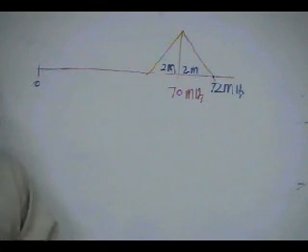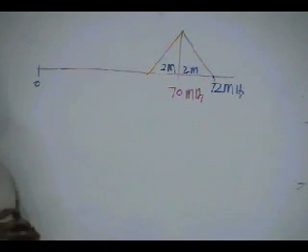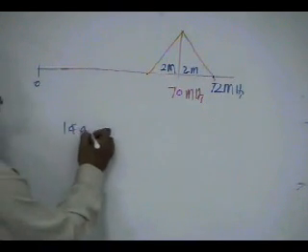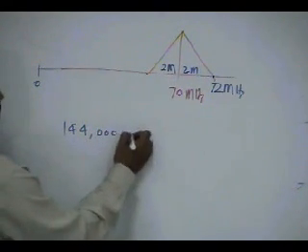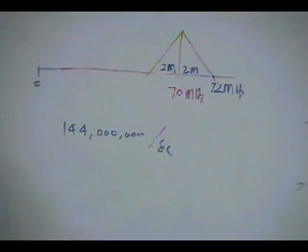144 megahertz. Very difficult to find such a fast A to D converter, number one. Then processing 144 mega samples. Just imagine, 144 mega samples means these many samples every second you have to process. You have to store, you have to process. If you do that, and this is very common, like 70 megahertz IF is very common.